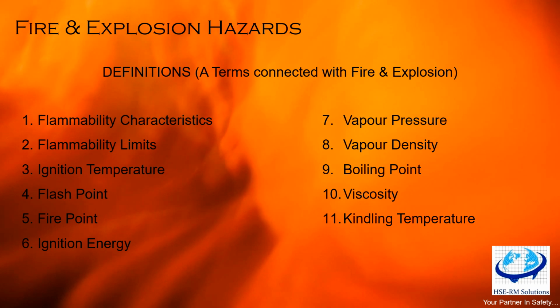So whenever we are asking how it happened, this is how things happen. You have to understand the vapor density of each liquid stored in your premises so that adequate provisions can be made, and you have to understand its characteristics, that this travels below, this travels above, correct? Now coming to boiling point. The lower the boiling point, the more volatile the substance and consequently the more hazardous it is, such as a flammable liquid. As the boiling point decreases, vapor pressure and evaporation rate increase.